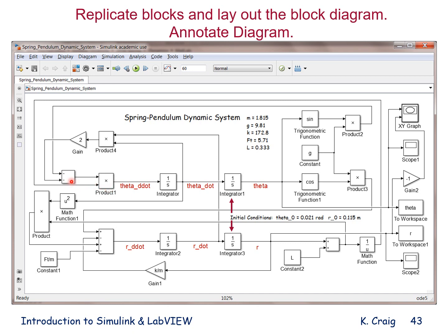The summing block has the summation of minus what? Minus the product of G and the sine of theta, minus 2 times the product of theta dot and R dot. And that is correct for one of the equations of motion, the theta double dot equation.